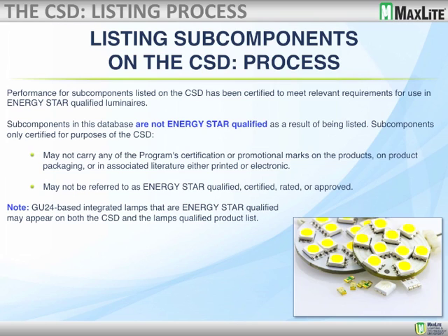Some components in the database are not Energy Star qualified on their own. They don't become Energy Star qualified until they are put in the luminaire itself, and that's important to understand. Because of that, they may not carry any of the program's certification or promotional marks, the logos and so on, and they may not be referred to in their literature as Energy Star qualified, certified, or approved, because in fact that doesn't happen until or unless it is tested within the luminaire that's to be Energy Star.